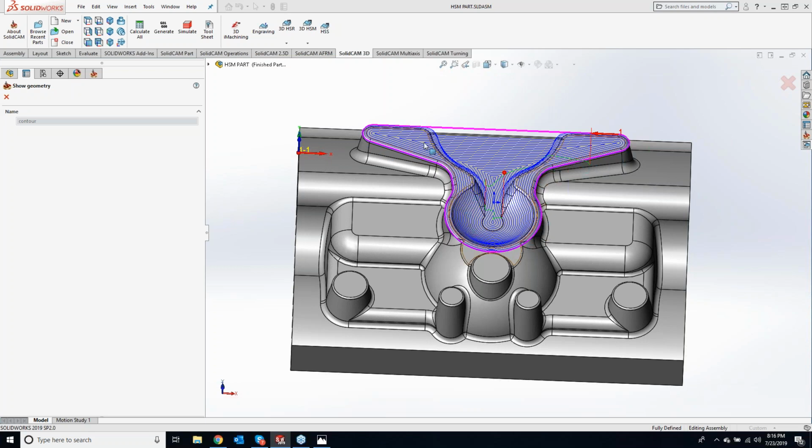So what we're actually telling it is we want to do a 3D constant step over contained to inside this boundary. With HSS, there is no boundary. Your boundary is the surface that you clicked on, and it's going to work on that surface. You can limit the boundary down by telling it to do a check surfaces under the gouge check, by telling it to click on all these different surfaces, but you're going to be doing a lot of clicking.